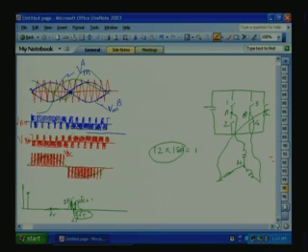Equal on and equal off rectangular pulse, we introduce notches in between. That means on the positive side, part of the time it will go negative, and on the negative side, part of the time it will go positive. So, notches are introduced so that the harmonics are suppressed. Can we introduce notches in such a way that the lower harmonics can be suppressed and the fundamental can be controlled? This is called selective harmonic elimination.